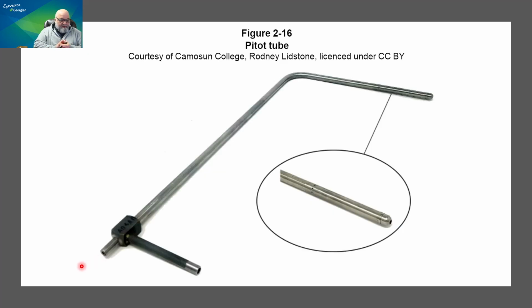All right. And here's the pitot tube. If you look at the pitot tube, you see that it has an opening at the tip, and that opening goes all the way in like that. And there are openings here which measure the static pressure. Here, it measures the static pressure. So it measures total pressure, and static pressure on both sides. And then this opening measures only static pressure. So the static pressure measured here and measured here cancel each other, and we are left with simply velocity pressure.